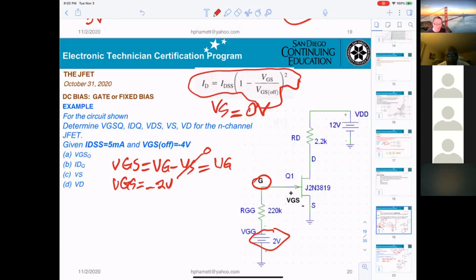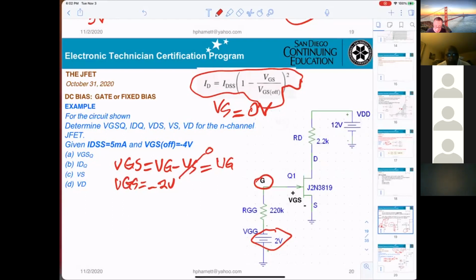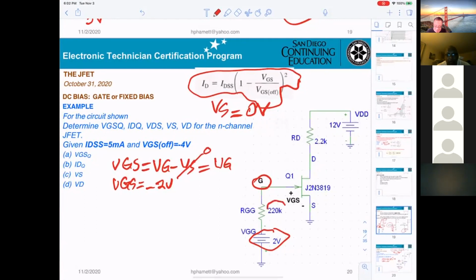I just explained to you guys, right? I said the current cannot flow through the 220K. So no voltage will be dropped through the RG. So whatever voltage on this side and the other side will be the same. Okay, but I thought that only occurs when we have a very high resistance, like 1 meg. Right. Now that 220K, that's enough. That's enough? Okay. All right, thank you.